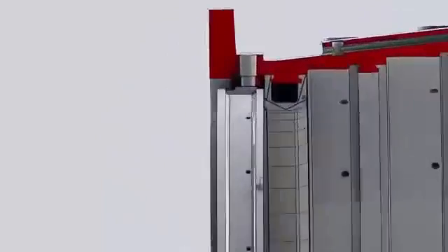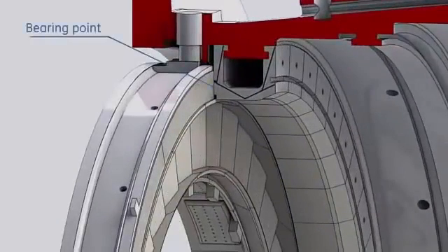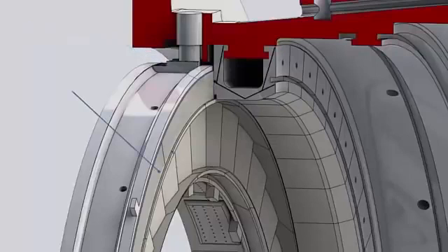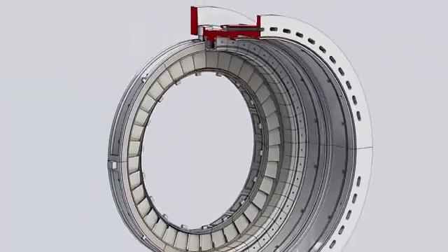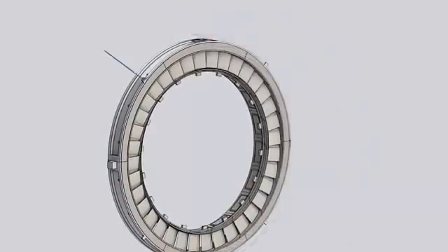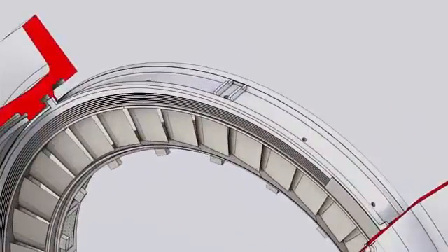The aft outer face of the retaining ring is loaded against the forward face of the first stage shroud, with steel strips in between to prevent compressor discharge air leakage between the nozzle and the shell. The nozzle 1 assembly is prevented from moving forward by 4 lugs extruding from the outside diameter of the retaining ring at 45 degrees from vertical and horizontal center lines. These lugs fit in a groove machined on the turbine shell.